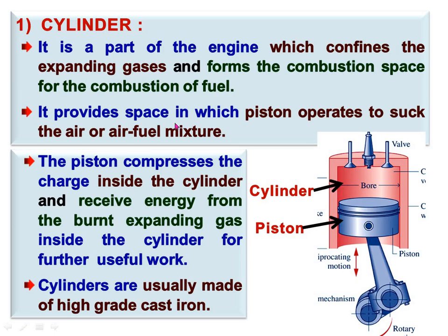Secondly, it provides space in which the piston operates to suck the air or air fuel mixture. Suppose our engine is a 4-stroke engine, in that case, during the suction stroke, or we can say intake stroke, air is sucked through the inlet valve in the engine cylinder.